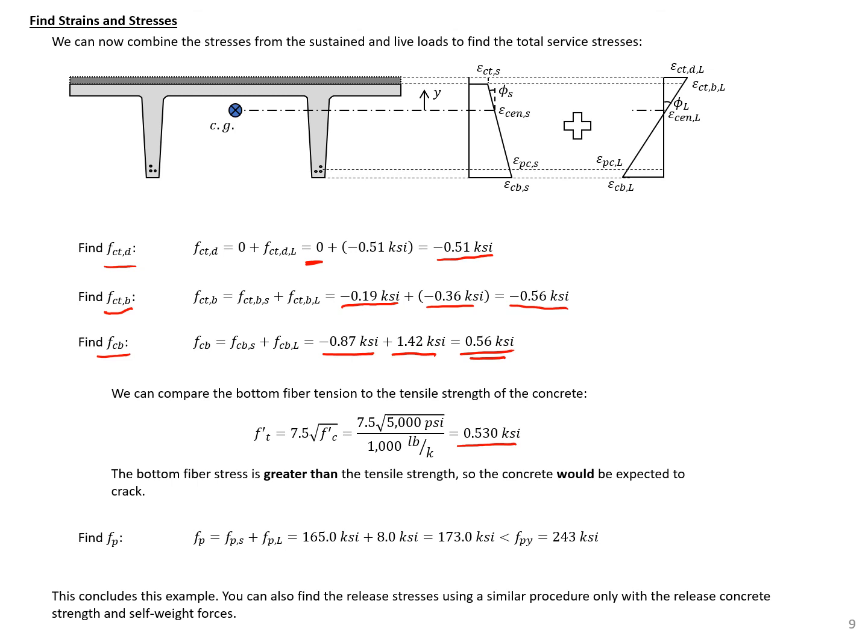And we can compare this value here to the tensile strength of the concrete and see that our applied stress is greater than the tensile strength of the concrete. So we would expect the section to crack. So this would not meet our stress limit checks.